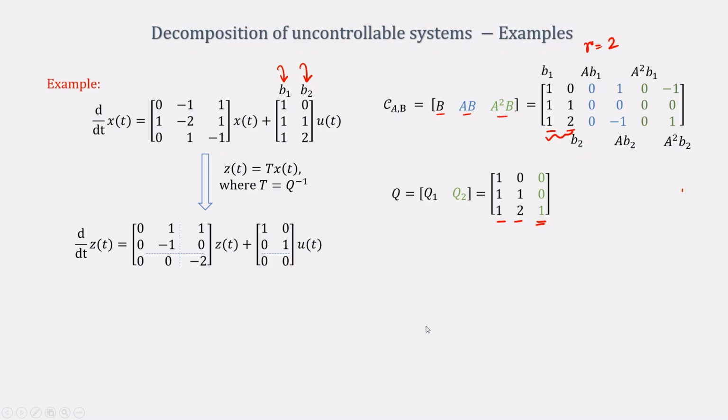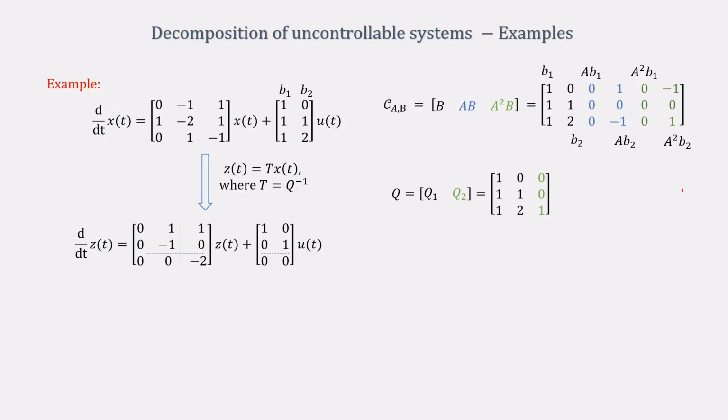So, this is how we can go ahead and find the controllability canonical form for an uncontrollable system. Remember that whatever I did for SISO has been extended to MIMO now, and whatever method I told for MIMO actually works for SISO also. So, why are we doing this?